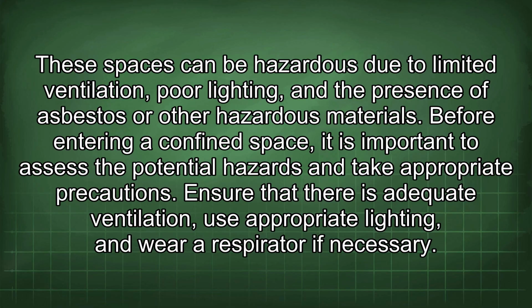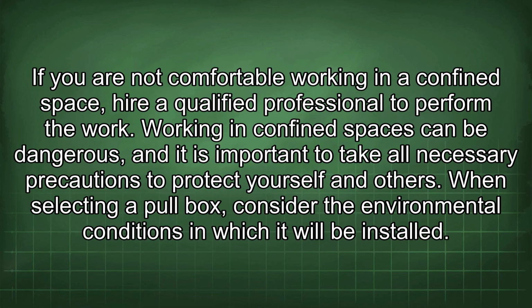Before entering a confined space, it is important to assess the potential hazards and take appropriate precautions. Ensure that there is adequate ventilation, use appropriate lighting, and wear a respirator if necessary. If you are not comfortable working in a confined space, hire a qualified professional to perform the work. Working in confined spaces can be dangerous, and it is important to take all necessary precautions to protect yourself and others.